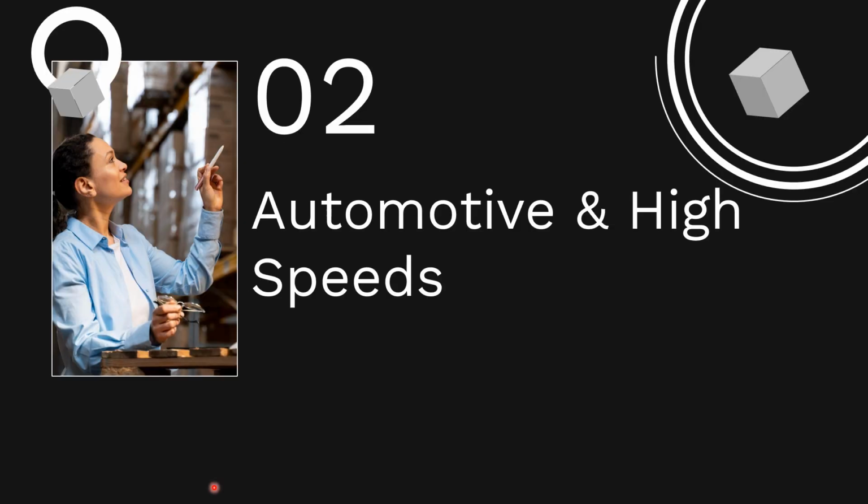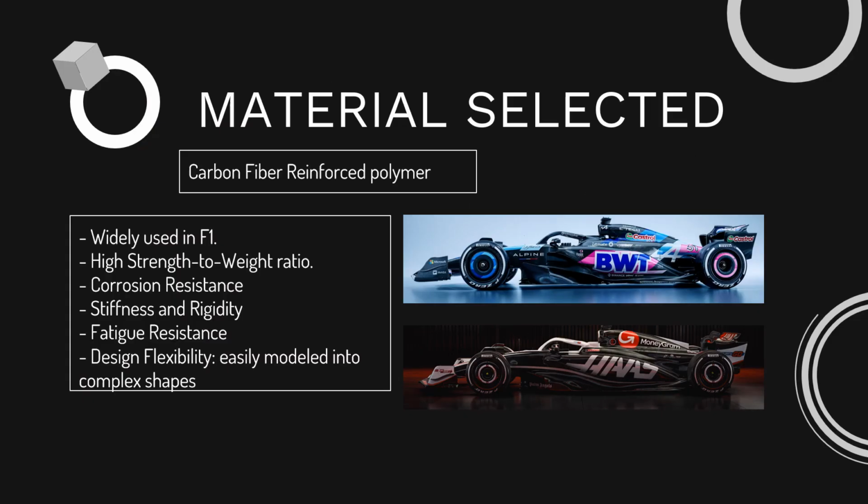Now the second project is based on automotive and high speeds. So I'm basically choosing the carbon fiber reinforced polymer with some resins. Basically, carbon fiber is the most used material in Formula One. This is because it has a high strength to weight ratio. Weight is crucial in Formula One in order to improve the lap times.